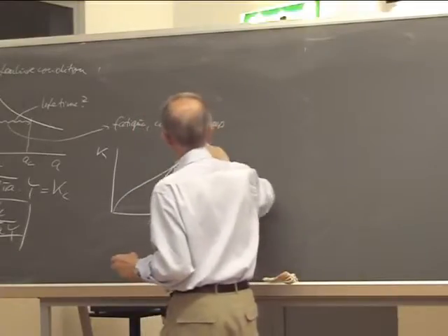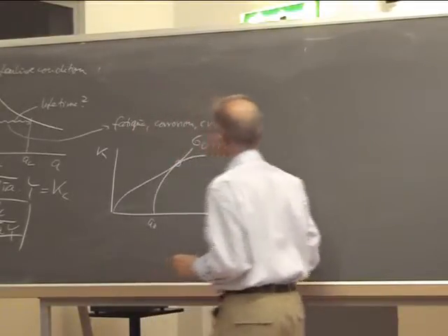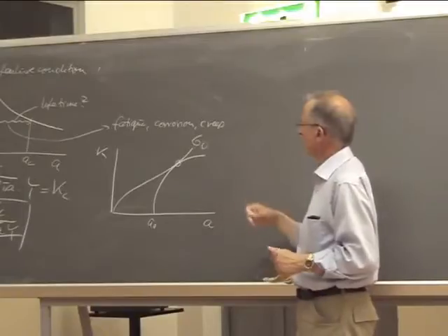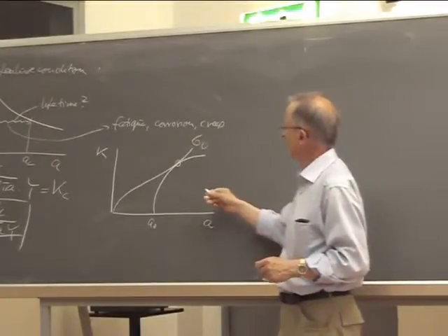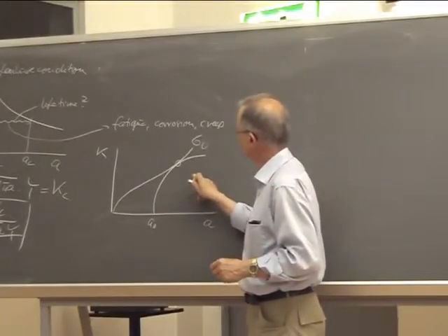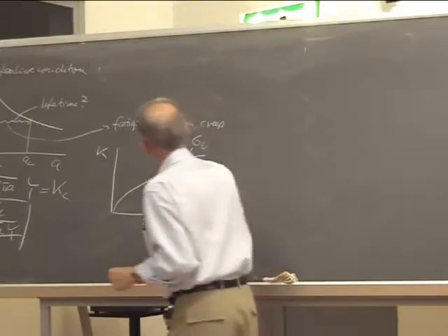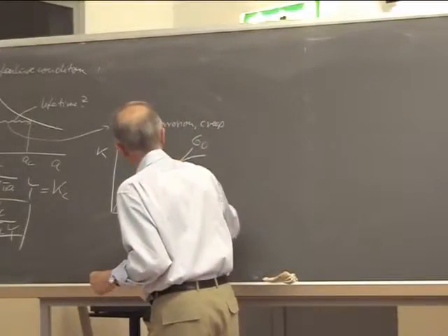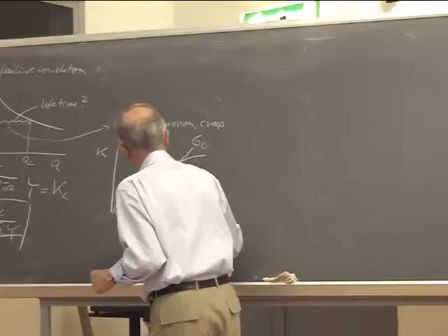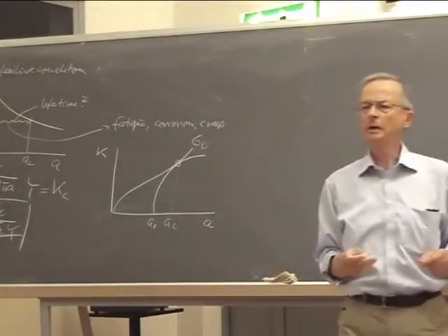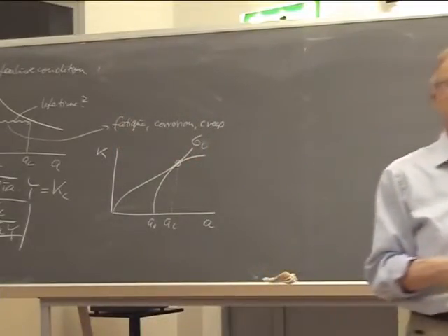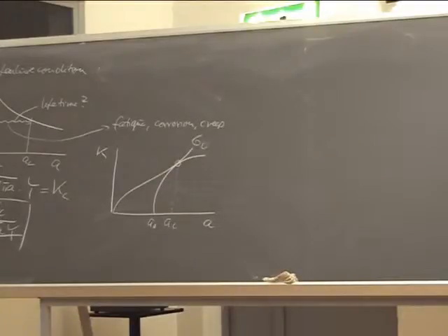And this is then the critical stress. You remember the critical stress or force or whatever we label the diagram here. And at the same time, we find the critical crack size, which can be of the order of centimeters or tens of centimeters or whatever, so quite substantial.